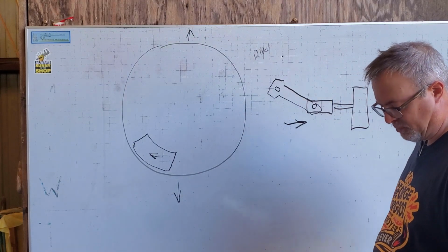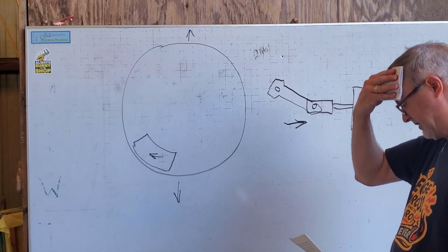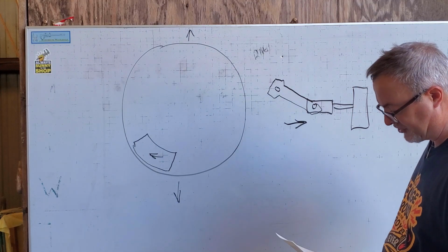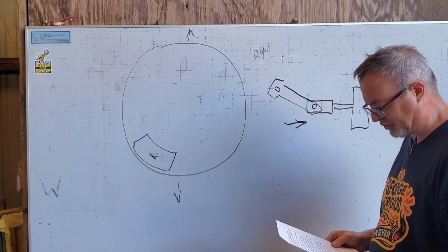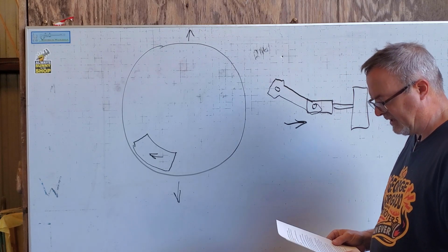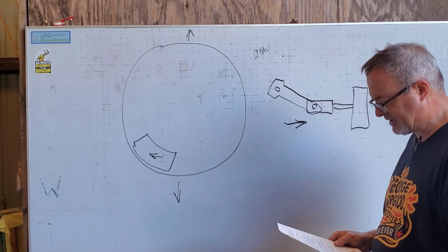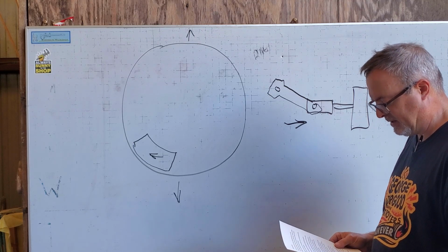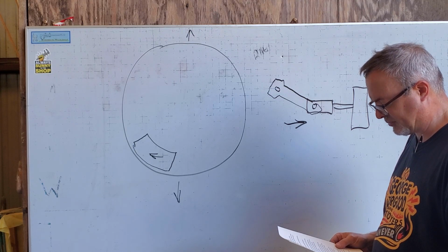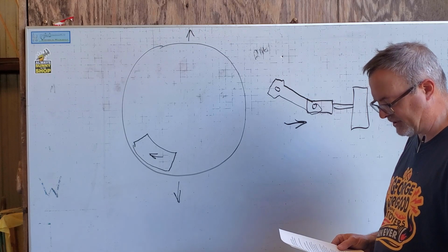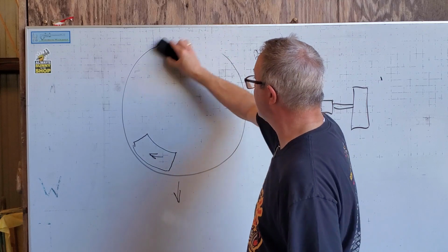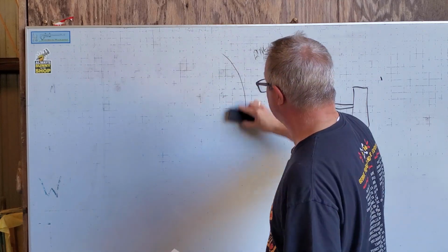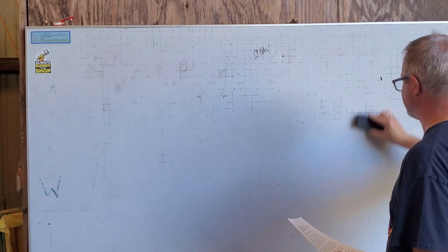Number 5, the point at which the exhaust port closes, compression, is important since this allows pressure to build up in the opposite end of the cylinder to cushion the reciprocating parts and allow the transfer of forces from one side of the crank pin to the other. The energy in this compressed exhaust is returned to the engine since it increased the pressure in the cylinder just prior to admission. I've read quite a bit about this, and in my mind, the jury is still out.